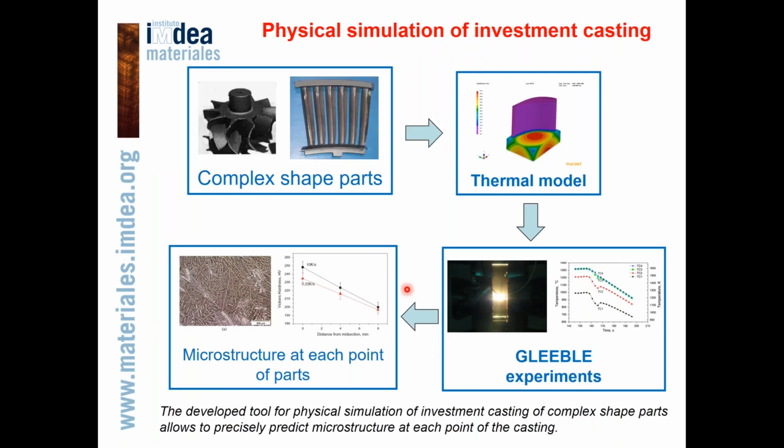So we can conclude that the combination of thermal model and Gleeble melting solidification experiments, followed by thorough microstructural characterization of Gleeble samples, allows us to precisely predict microstructure at each point of the casting. And this is very valuable information.